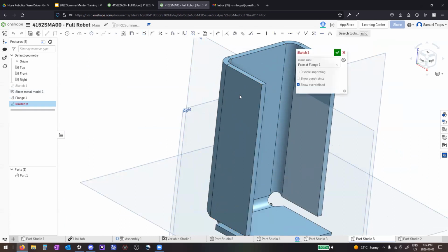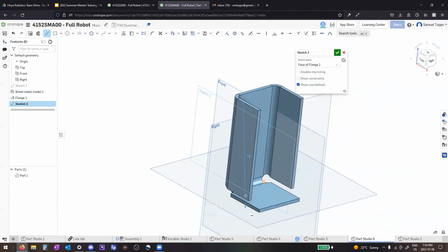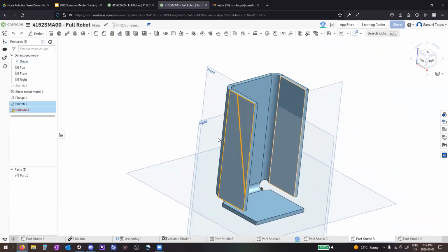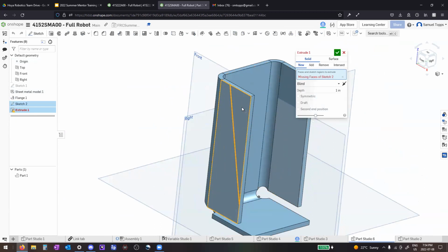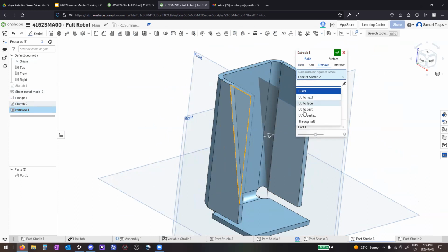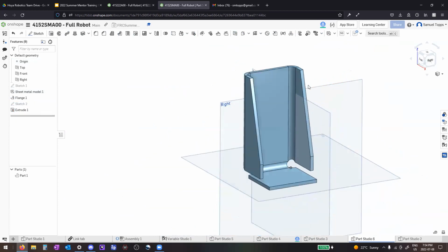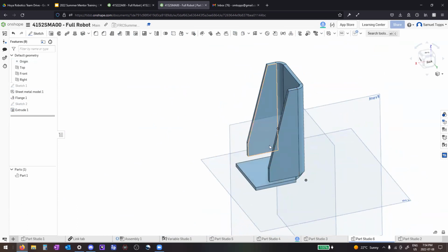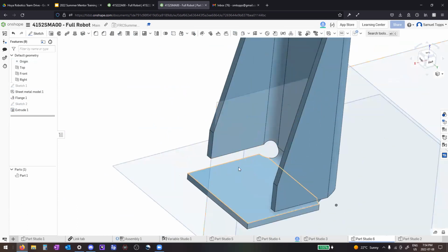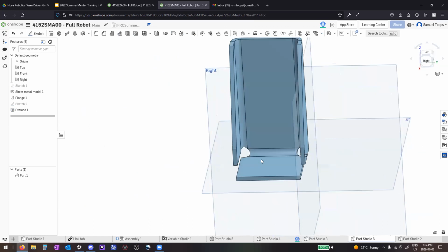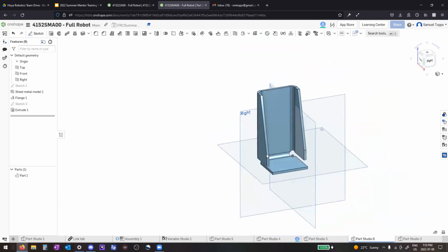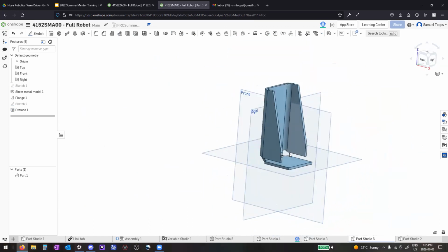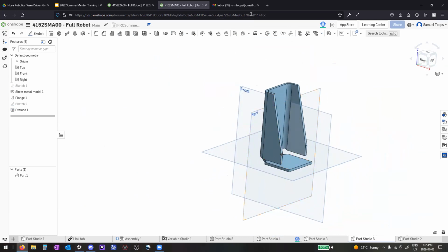And we can still edit this model after. So if I want to cut an angle off of this piece, I'm not going to dimension that right now. I could just remove a nice angle off of that. Maybe someone's going to put a weld down here, make it like a really strong bracket or something. Yeah, that's kind of the basics of the sheet metal tool, I guess.